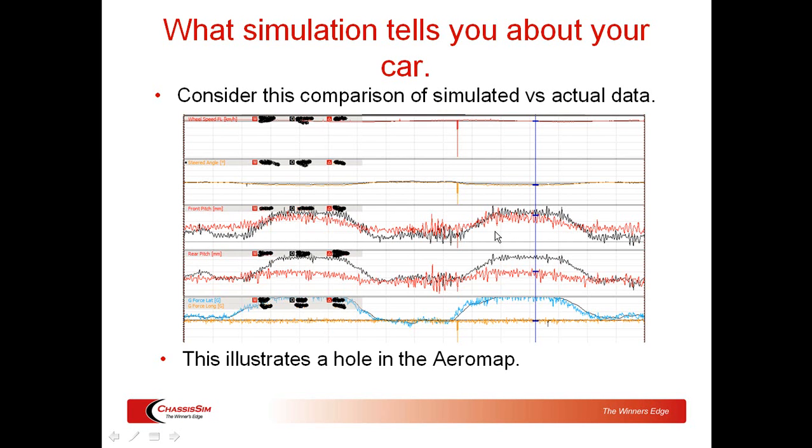Now, looking at the two plots, the front pitch isn't too bad. The rear dampers, there's a really big discrepancy there. Most people at this point would take one look at that, throw their hands in the air and figure, we've just shoved 15 grand down the toilet. Well, I can tell you right now, you haven't. Your simulator has just told you there's a very, very big hole in the Aero map and that you need to do something about it.